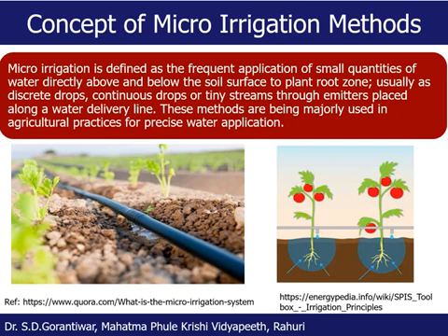But in case of the micro irrigation method, what we can do is that we can apply the exact amount of water. Say for example, today my water requirement is 2.3 millimeter, and for that, say if I have to apply 473 milliliter of water per nozzle or per plant, then it is possible by means of the drip irrigation method, by means of the micro irrigation method.